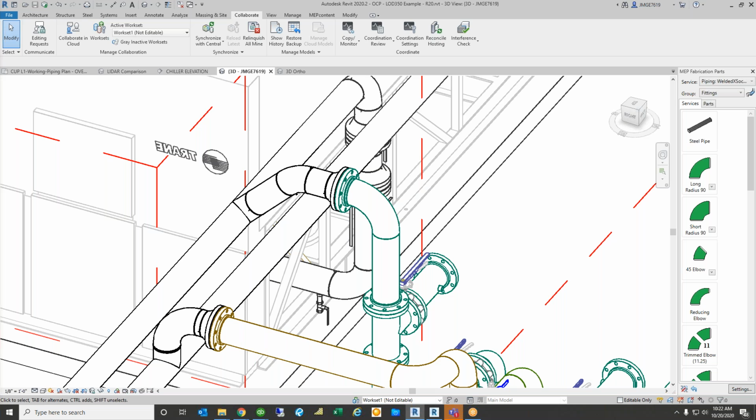If I give a Revit model to a contractor, and the contractor does all their fabrication work and all their as-building work in a separate software platform, that information can't simply be reopened in Revit and boom, you have as-built. There is a process there to align what has been done in the field with Revit. So on projects where I've done LiDAR scanning where an existing Revit model exists, we take that existing Revit model and identify those interface points that are captured with the LiDAR scan, and we make adjustments to those points of connection in the Revit model to make sure that it is as-built correctly, and then we can go from there.